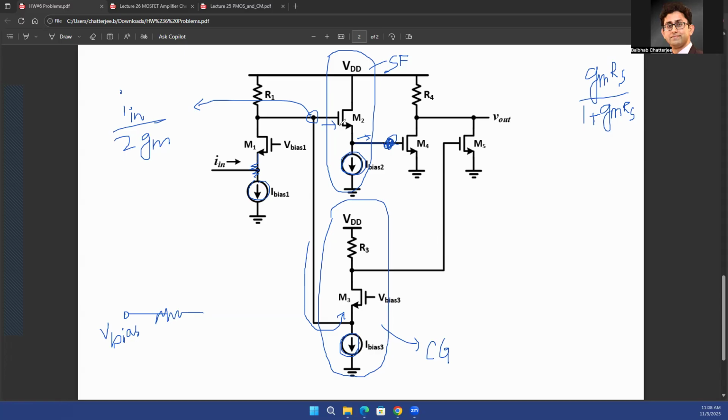In a real MOSFET, the gate does not have zero leakage. It does not actually have infinite impedance because, as you know, infinite impedance doesn't exist. It will always be some finite impedance. That means there is always going to be some finite current flowing through the gate. Now, all these wires will have finite resistances as well. So as soon as you have wires with finite resistances and a leakage current flowing through them, there would be a voltage drop across this resistor. So even though you wanted to apply V bias at the gate or at the source or whichever point you want to bias.